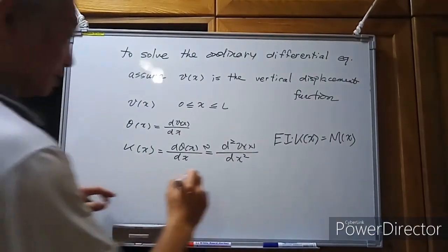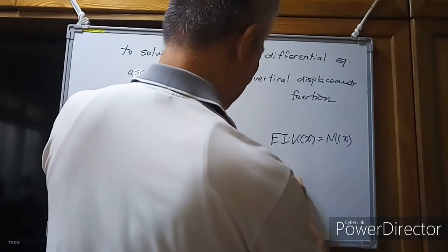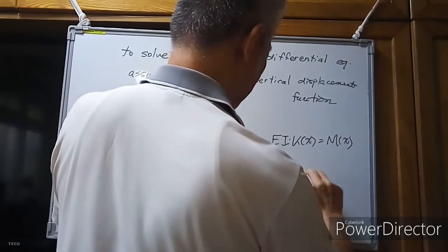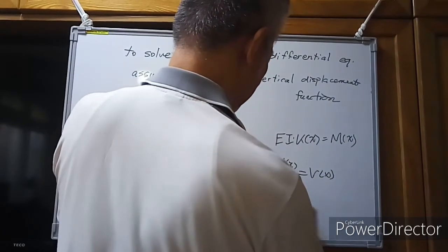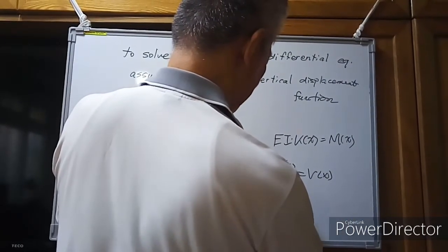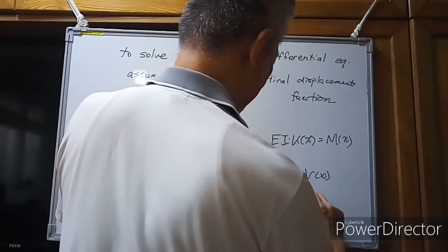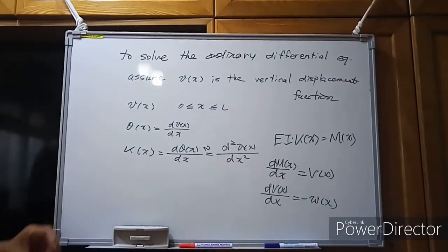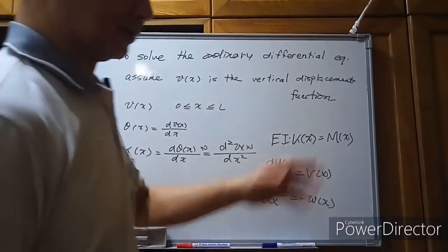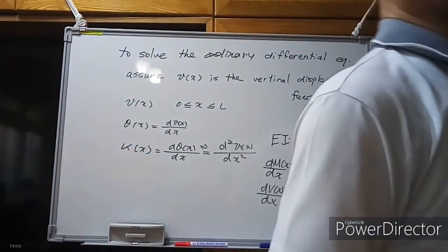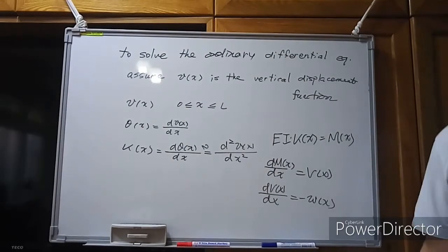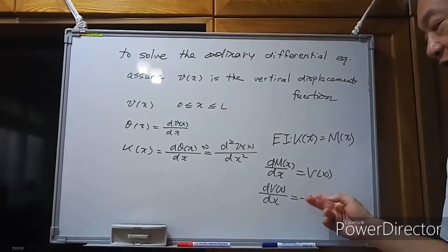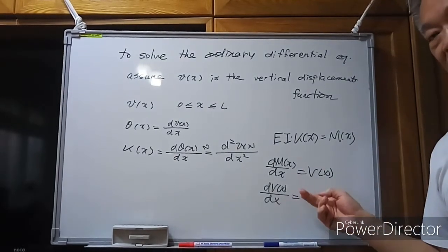Also, if we take the first derivative of the bending moment, then we can get the shear force. If we take the derivative of the shear force, then we can get the distributed loading.